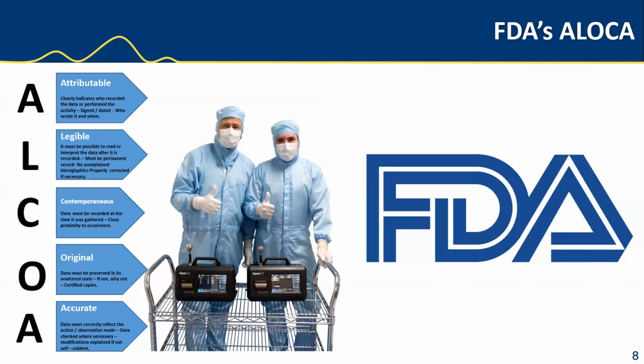Contemporaneous. Backdating data can lead to errors, and information captured only at the end of the day can be forgotten before it's captured. So in this instance, contemporaneous means that the data must be recorded at the time it was generated. If this isn't possible, it must be recorded as close to the observed event as possible. The data integrity requirements request timestamping without manual operation, and recording devices and computer time clocks must be synchronized across the system. Sounds a bit like a real-time monitoring system to me.